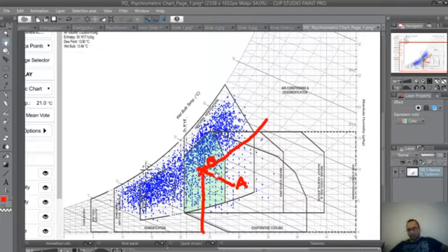On the psychrometric chart, the shift between A and B represents cooling down the air by evaporative cooling. The relative humidity increases, the air temperature drops, and the absolute humidity, which is on the vertical axis, between points A and B also increases, since water vapor content is added to the air volume.